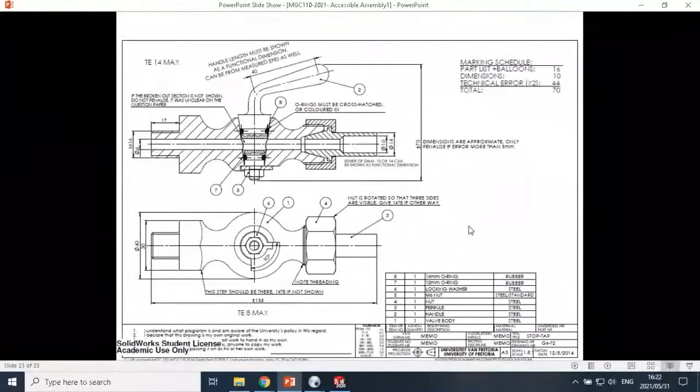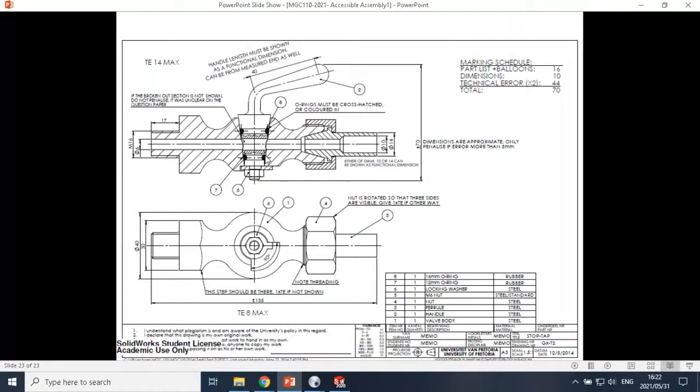So that's basically what it looks like when we do the section drawing of this component. We need to show three kinds of dimensions. Overall dimensions, so that's the overall length, overall width, overall height. In this one's case, calculating the height was a bit tricky, so we gave you up to 5 millimeters either way. Then mounting dimensions: we could consider this thread on the end as a mounting dimension, so that 17 long M16 thread can be a mounting dimension.